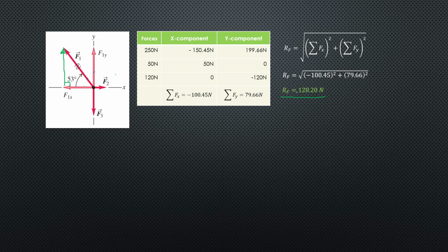Now, solving for the angle, we always use this formula: tangent theta will be equal to opposite over adjacent, so y over x. So tangent theta will be equal to the summation of forces along y over the summation of forces along x.